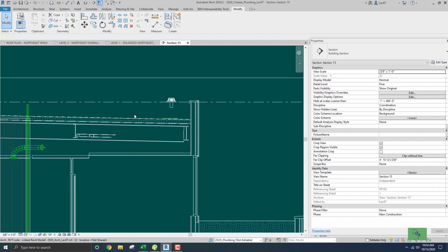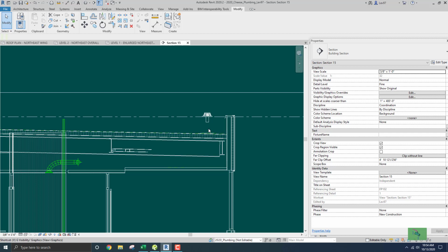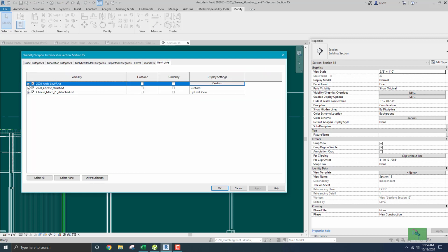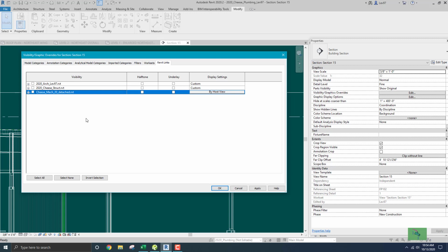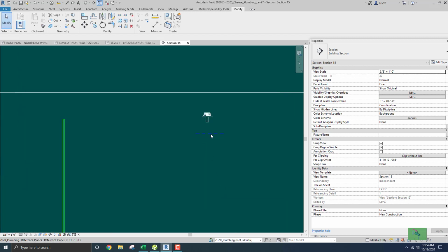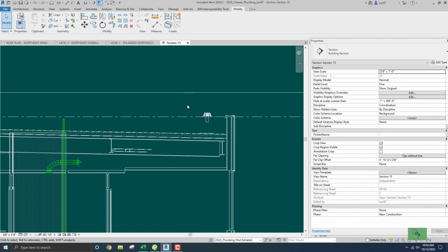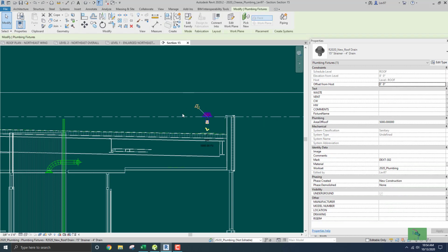Okay. Let's look at that section, because what I'm going to need to do is bring it down to this roof area. So I'm going to turn off the architects and the structure and the mechanical, so that I can see the reference plane. And the reference plane is roof 1 ref. Undo that and change the reference work plane. I'm going to edit the work plane, right? So it looks like I'm not going to be able to get down to the floor with this because of what's going on. I still don't know why that changed.